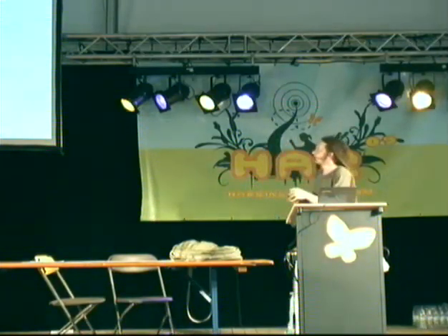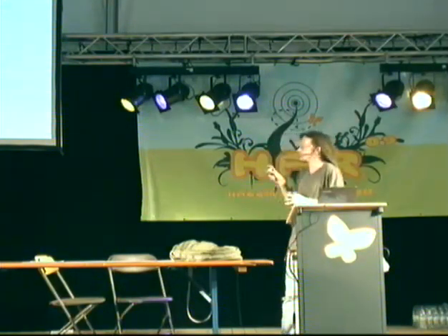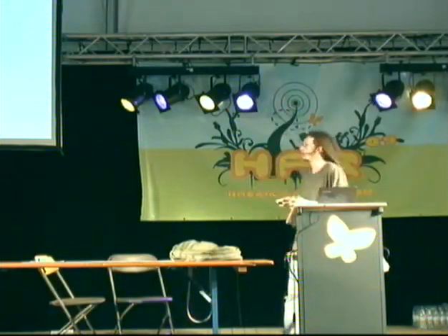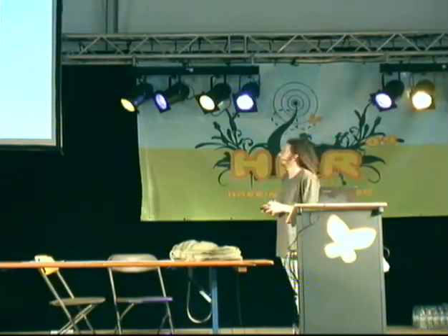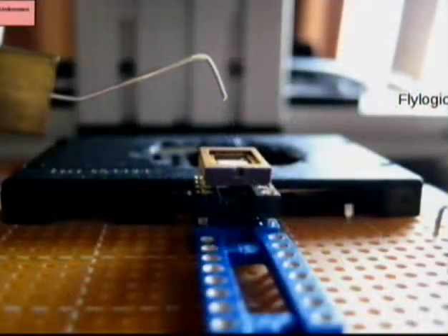And this is secured by either an EEPROM fuse, which can be attacked by ultraviolet light, or by a physical fuse, which is actually broken. And that requires probe needles. So this photo I took of Christopher Tarnowski from FlyLogic actually sticking a needle into a SIM card to tap the internal memory bus. And you can actually see the needle right here on the left. And this requires a lot of skill and a lot of equipment.